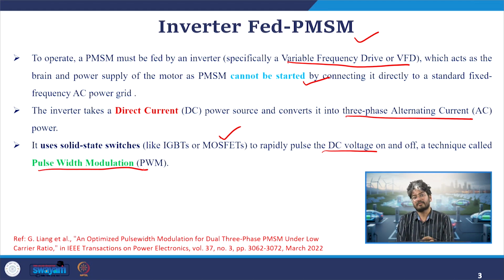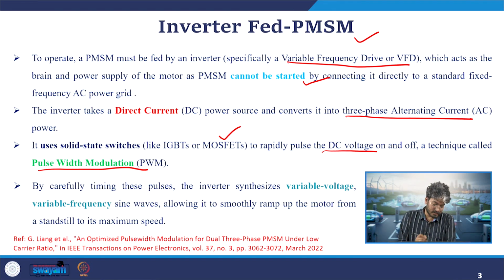So the PMSM can be run in very different methods of control. Classical control, and we have vector control also, where we will be going for decoupled frame, which we have also seen in brief while we were discussing our converter topic. So here it will be synthesizing a variable frequency and variable voltage AC signal, which will be sinusoidal in nature, because our AC is generally considered as sinusoid in nature. Okay, so it will be operated at variable frequency and variable voltage.